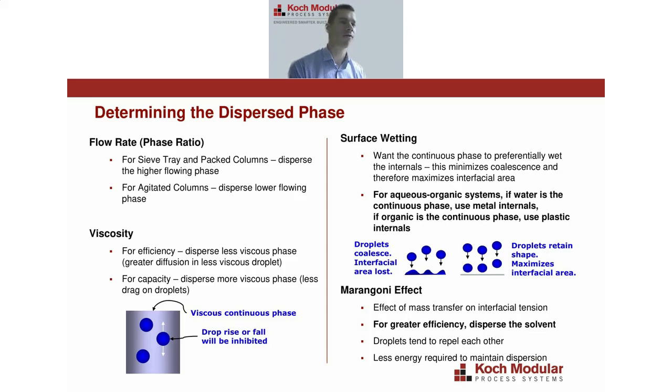And one benefit of pilot testing is that although we'll make this judgment call prior to running a test or prior to coming up with a preliminary extraction column design, you can run an extraction column both ways and switch the dispersed and continuous phases halfway through the pilot test if you need to really determine which is ideal for the highest amount of extraction for a given application.